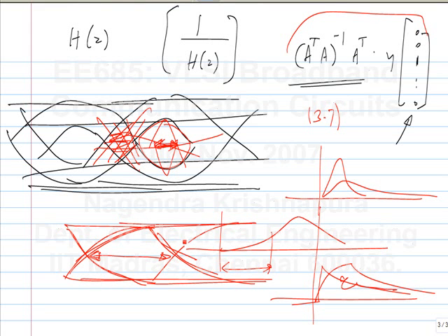No, but what is the number of coefficients you get with that? Infinity, right? So that's the problem. If you invert it, you get infinite number of coefficients. So you truncate it to some limits. That is the zero forcing case. But that case also introduces a lot of noise. If you add noise, that introduces a lot of gain to the noise. So you do minimum mean square error, which performs better with noise. We haven't proved it, but you can take it that it does in fact do better.